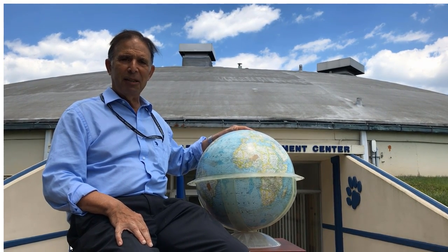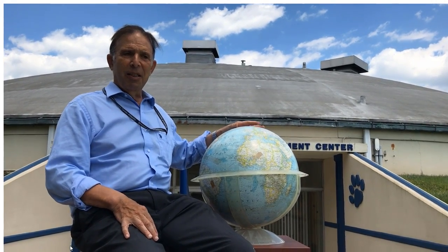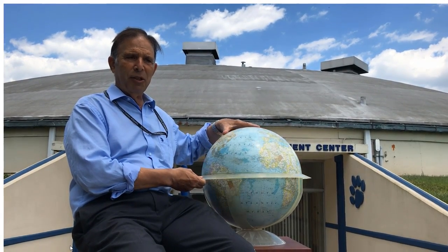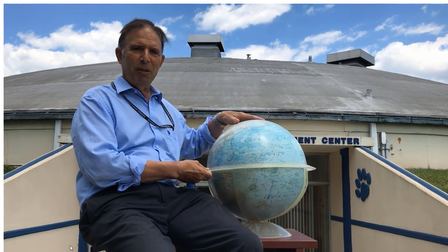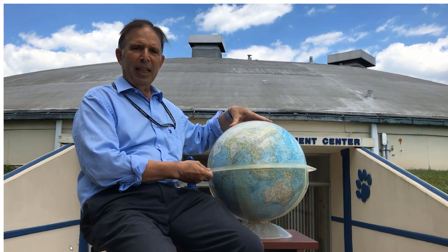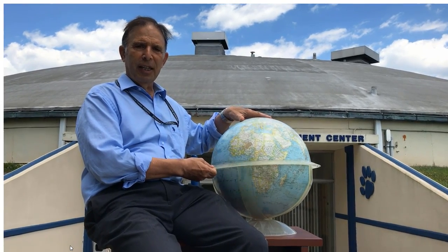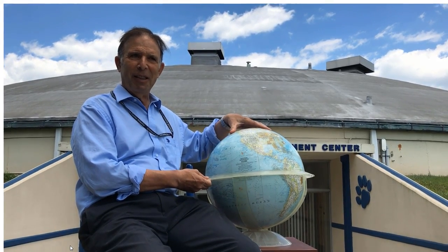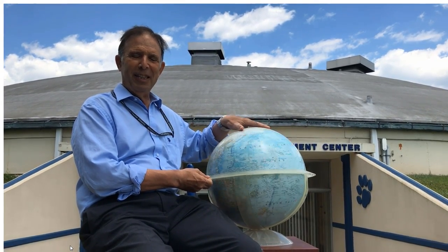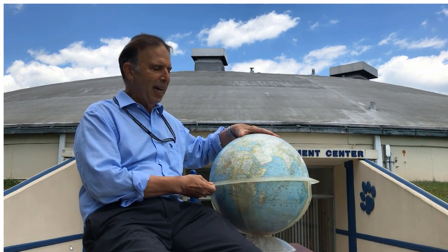Hello, this video is to remind you of the three predominant types of angular motion that a vehicle experiences as it traverses the Earth. The first motion is simply rotation of the Earth at approximately 15.04 degrees per hour in the polar direction. That translates to omega cosine latitude in the north direction, 0 in the east direction, and minus omega sine latitude in the down direction.